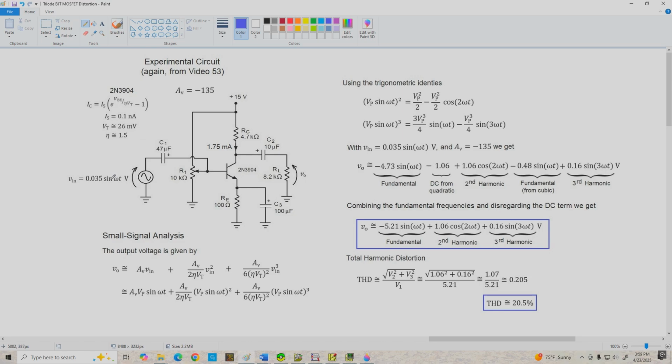When we substitute in this sine function, we get this messy looking thing here, and in order to make sense of this, we have to expand the sine squared and sine cubed factors using these trigonometric identities. And if we take a second to look at these trigonometric identities, we see that the sine squared is going to result in a DC component and an inverted cosine waveform at twice the original frequency.